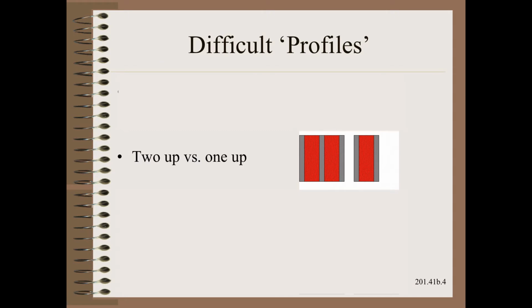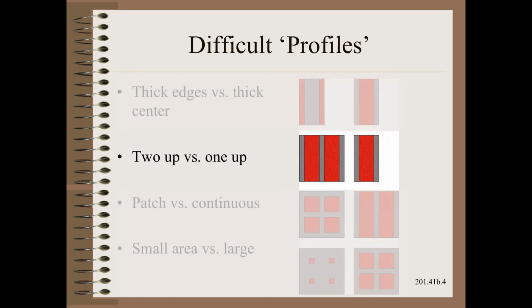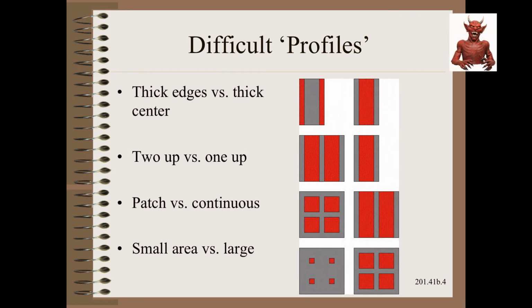Here I offer yet another stern warning having to do with profile, but this time it is intentional profile variation as part of product design. Here I will just mention that going too wide is not just twice as hard, it can be an order of magnitude more difficult because there are many problems such as registration and wrinkling that do not exist in that form on one-wide webs. There are many other products from hell that I cover in my seldom taught Web 101 module that I call DFM, or Designed for Manufacturability.